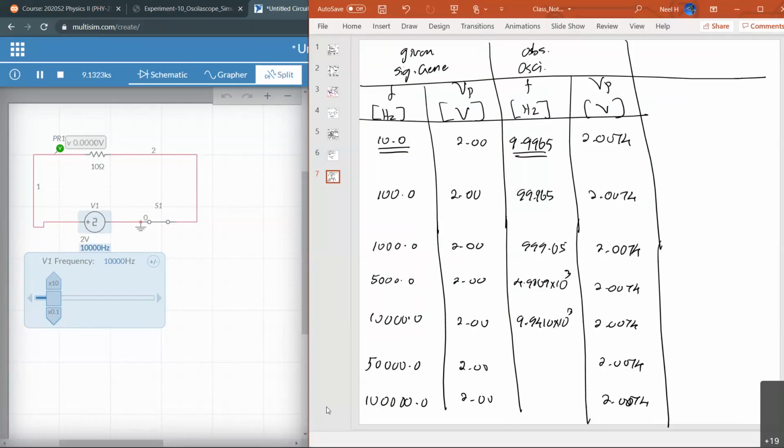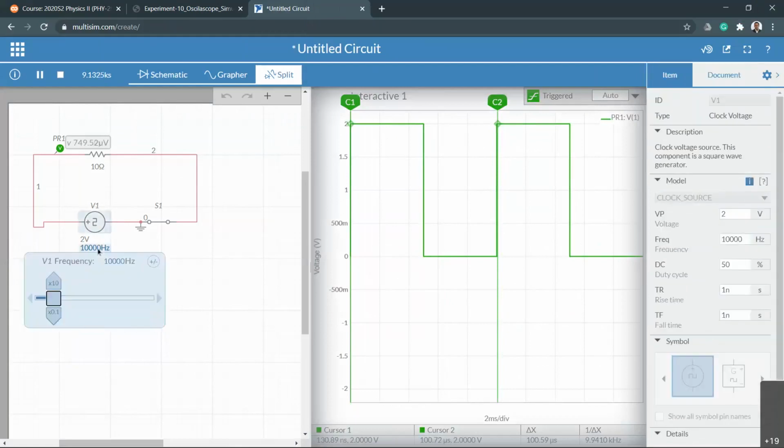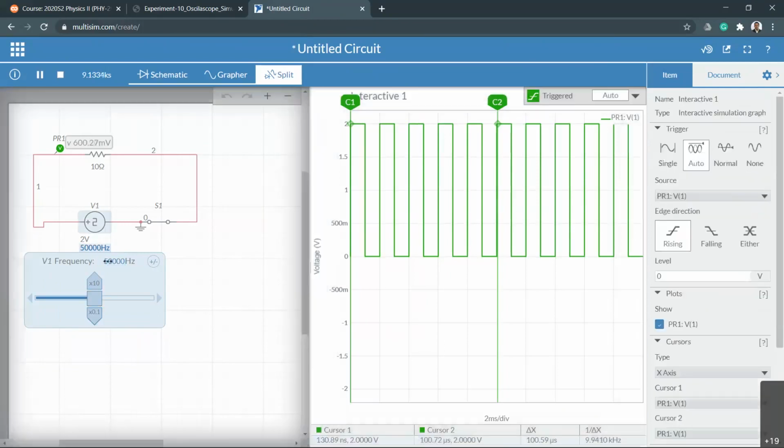Okay, now I just need to read these two, right? So you just need to change your frequency to 50,000. Now, if you're doing this as an experiment in a circuit, you can switch on and switch off 50,000 times per second in that circuit. That's the idea of frequency. So 50,000, hit enter, and then you have to change the x-axis again. Click here.